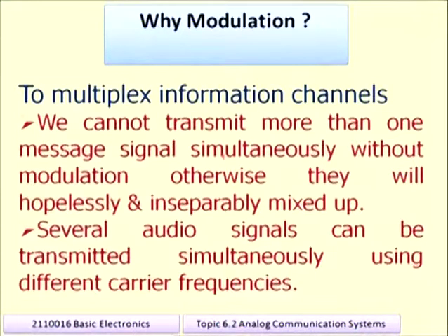So another possibility is that without modulation you cannot transmit signals simultaneously, but if you do the modulation, it allows you to do frequency multiplexing, and because of that you will be able to transmit so many messages simultaneously. So that is another motivation behind modulation.